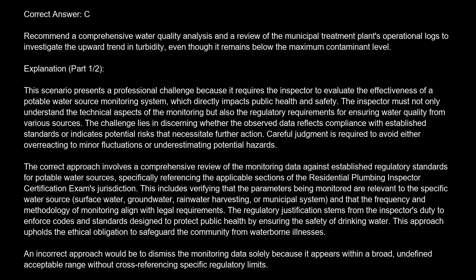The correct answer is C. Recommend a comprehensive water quality analysis and a review of the municipal treatment plant's operational logs to investigate the upward trend in turbidity, even though it remains below the maximum contaminant level. Explanation: this scenario presents a professional challenge because it requires the inspector to evaluate the effectiveness of a potable water source monitoring system, which directly impacts public health and safety.